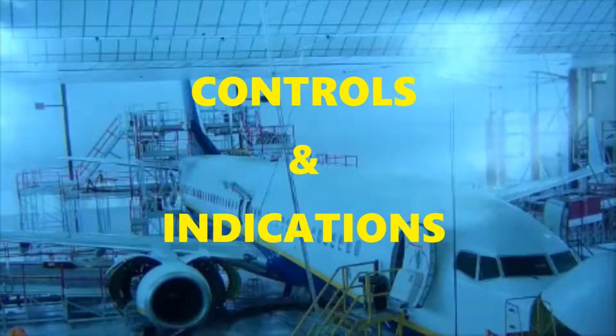Okay, now what if it's amber but it's a horizontal line, not a vertical line? Okay, so that's going to mean the opposite of closed, right? So remember, amber horizontal is going to mean that the valve is open with the crossfeed push button selected off.